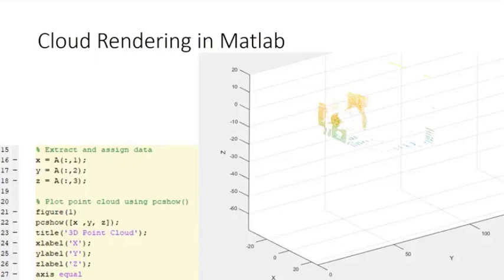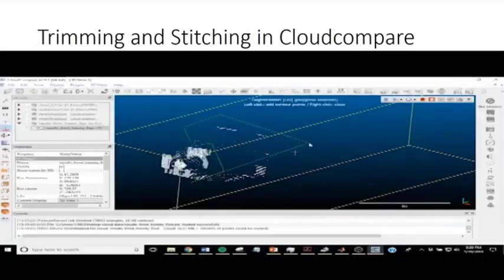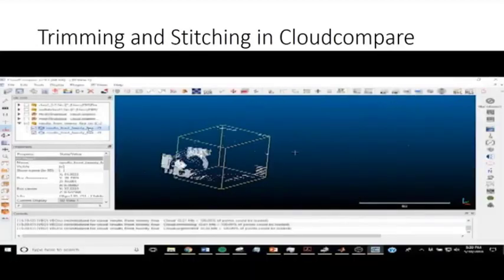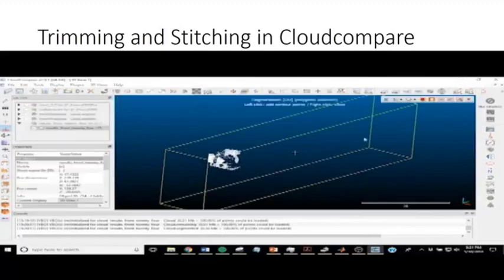Once I collected my images, I ran them through the Python code. With my clouds for each scan saved as text files, I plotted each cloud in Matlab to confirm that they came out okay, and then loaded the clouds into Cloudcompare. I used the segment function to crop out any stray points from the noise and other structures that came up in my scan.